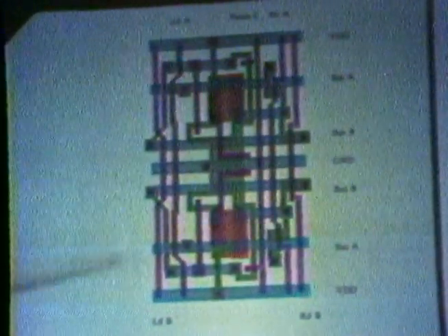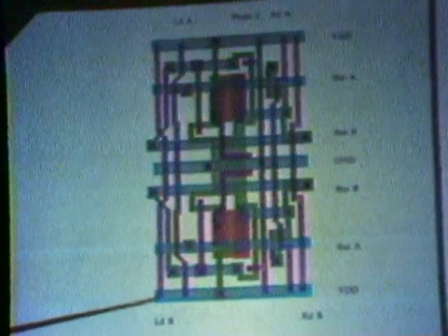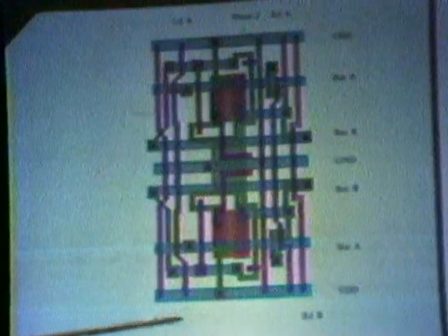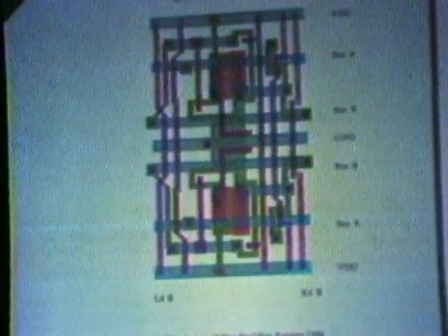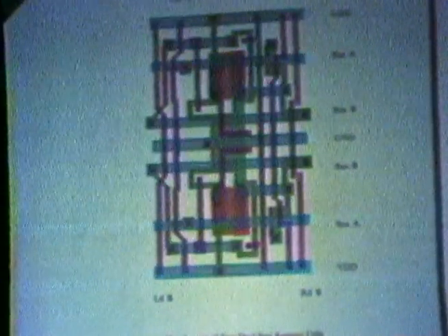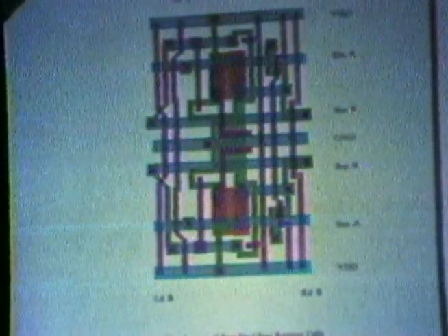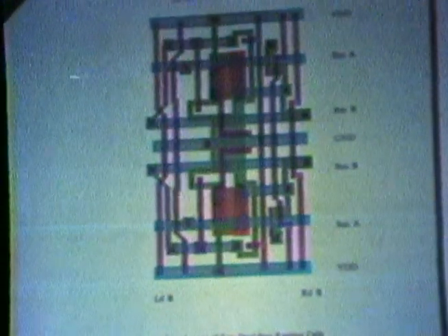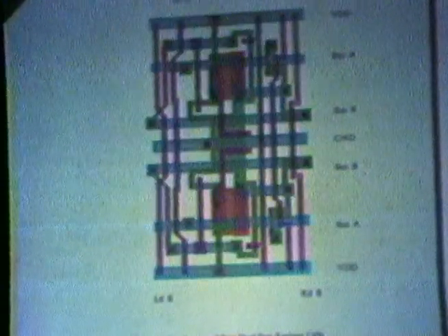The vertical red lines are the control lines, which are essentially gated clocks: load from the B bus and read from the B bus, and load from A and read A, and then there's a phase 2 line that always does a refresh operation on every cycle. I don't want to go into the details of this too much. You can read about it in Chapter 5, but let me just show you how it fits into the overall layout of the OM2 data path chip.